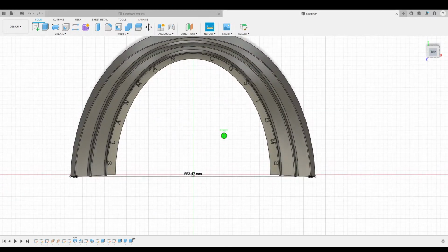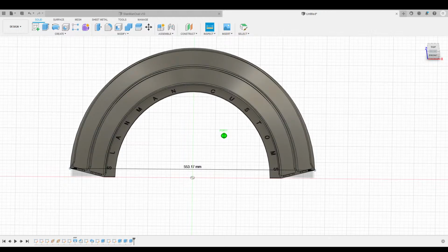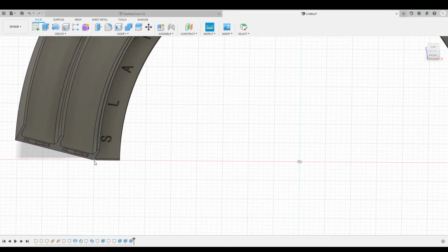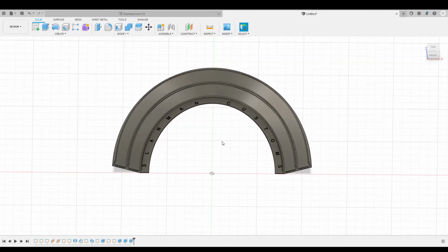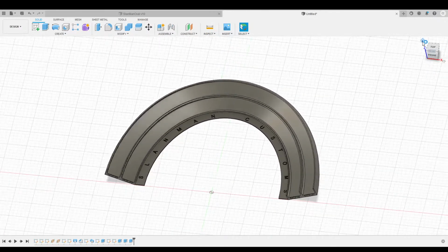So what we have to do is split this thing up. And to do that, we get out of this measure. One of the pitfalls is you can sometimes have this measure tool just be chilling over here and nothing will work, and it's because the measure tool is still saying, hey, I want to be measured. But you can see that our original profile is still the 400 millimeters, just like we specified at the beginning. Okay, so that's done there.